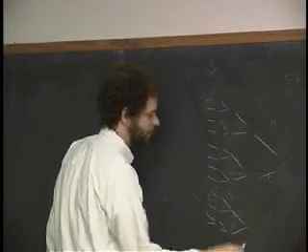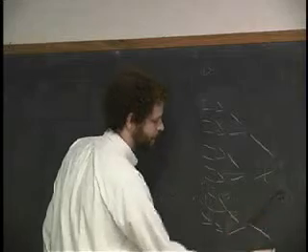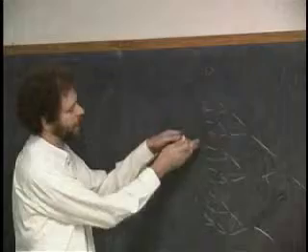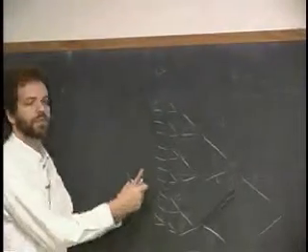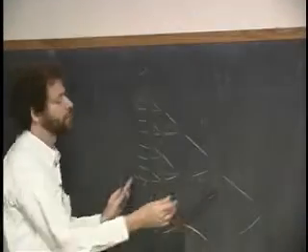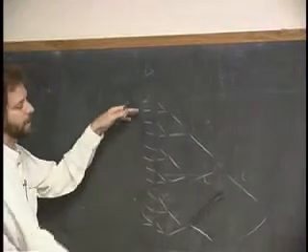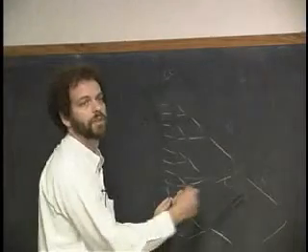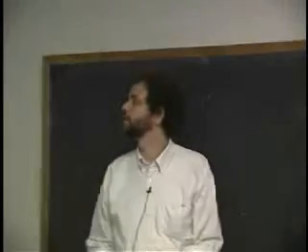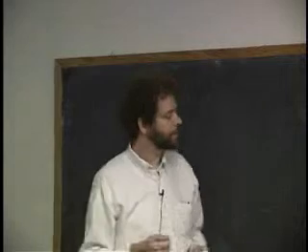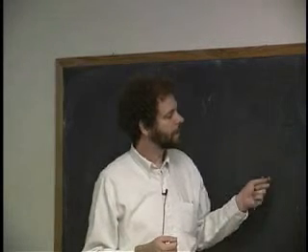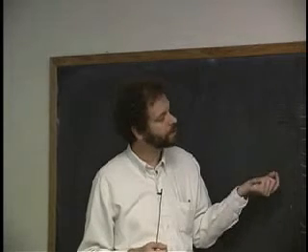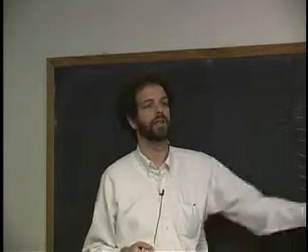We've run out of room here, but we'll just pretend that there's more. And you build a tree like this. If you have n elements here, the depth of this tree is going to be log n. And so as the number of elements that I need to choose from grows, the depth of this tree is going to grow too, with order log n depth. And so that tells you that the speed of the memory system, the latency of trying to get to a particular bit here, is bound by log n as n gets large.